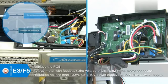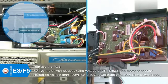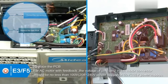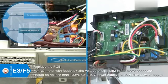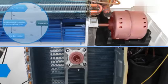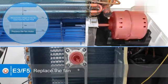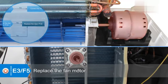Examination for main PCB board. AC motor with feedback. Turn the power on and set the unit as running in high-speed mode. 15 seconds later, measure the voltage of pin 1 to pin 2 in the fan motor connector. If the value of the voltage is lower than 100 volts for 208 to 240 volts power supply, or 50 volts for 115 volts power supply, the PCB must have problems and needs to be replaced. If the value of the voltage is normal, the fan motor needs to be replaced. If the error still exists, replace the main PCB.